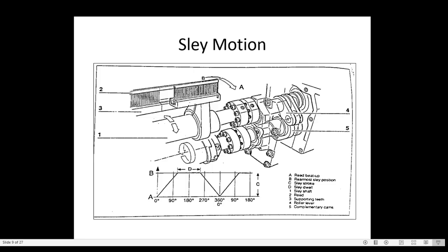To control this sleigh is very difficult, and the load on the machine drive is coming, and breakage of machine part may be there if eccentricity ratio touches 1. So always see that eccentricity in the conventional loom should not be up to 1, it should be very small, 0.50, 0.60. So this eccentricity is not there in the sleigh motion. In the shuttleless loom we are having dwell. So this is the basic difference we can see here.